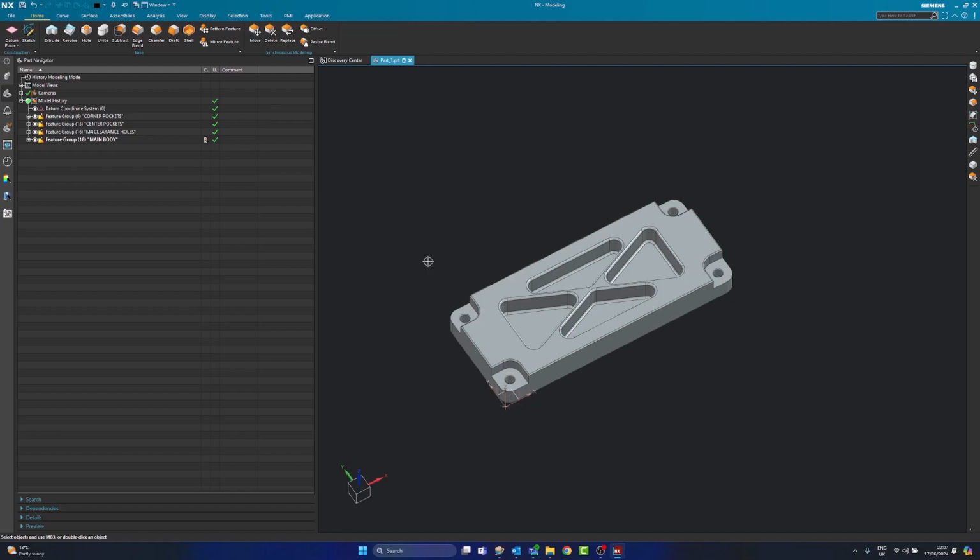And now when parts start to get a little bit more complicated, so let's say you've got 3 or 4 or 5 operations, you might have fixtures with operations there as well. It starts to really get messy. So what I like to do is I like to separate each part file out as operations. So we're going to have a part 1-op10 or op1, however you like to call it. Personally, I like op10, op20, op30. You could call it op1, op2, op3, so on and so forth. That's really personal preference, but I like to separate my CAM files out.